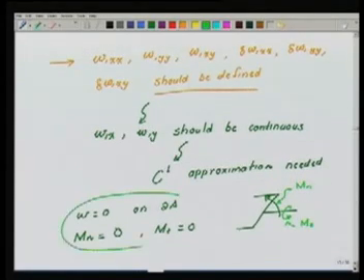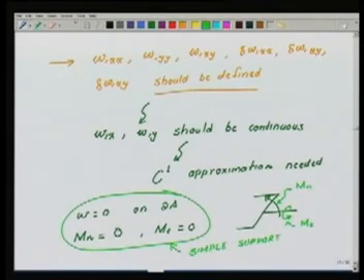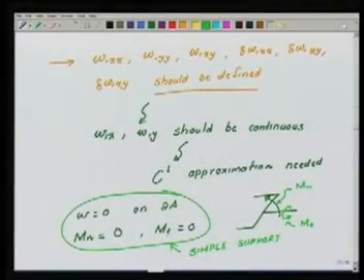This is one of the so-called simple supports. This is in fact a so-called soft simple support. You have a hard simple support also and so on. What if this edge was free? If an edge was free, on that edge your mn mt, that is the resultant moment, bending and the twisting, as well as the normal shear force V will also be 0. So that would be a free edge.